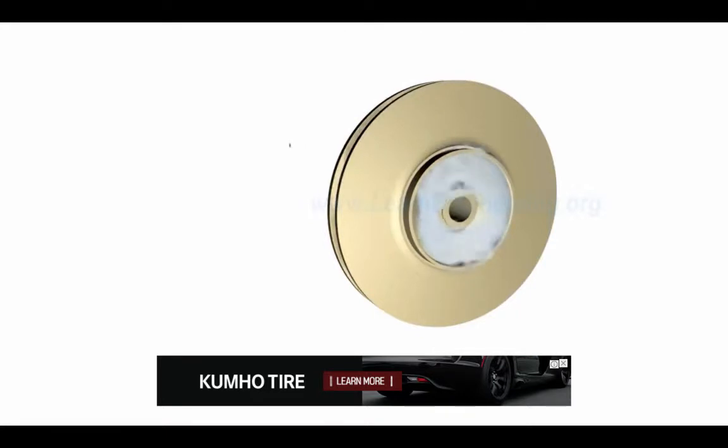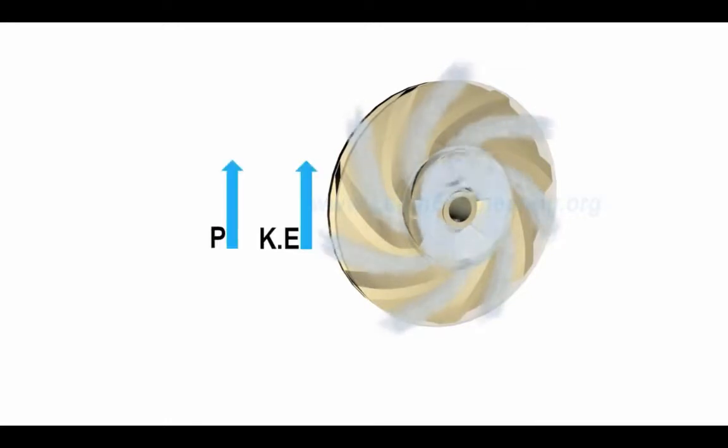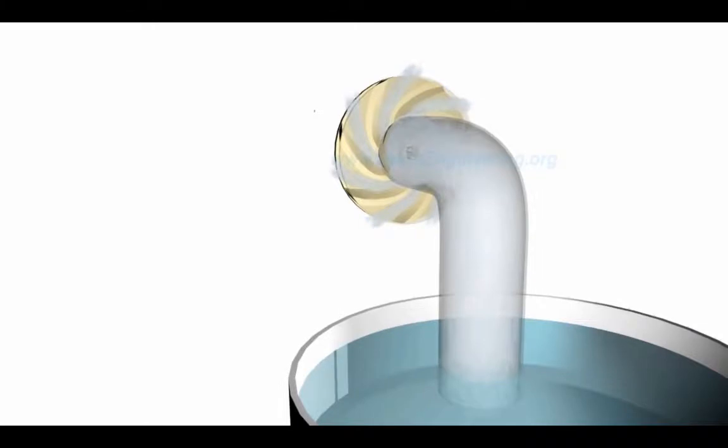This imparts centrifugal force to water particles, and the water moves radially out. Since rotational mechanical energy is transferred to the fluid, at discharge sides of impeller, both pressure and kinetic energy of water will rise. At suction side, water is getting displaced, so a negative pressure will be induced at eye. Such low pressure helps in sucking fresh water stream into the system again, and this process continues.